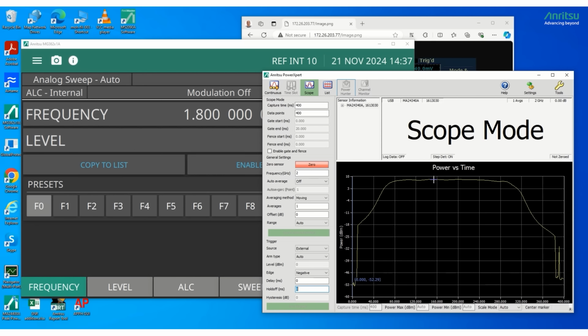I think it's measuring around 7 dB here, and then your stop band is around the same point, right? 53 dB, and then 7 dB. So 7 and 53, 60 dB dynamic range. You could get even higher by going higher in power. So you might get all the way up to 70 dB of dynamic range here with this measurement.